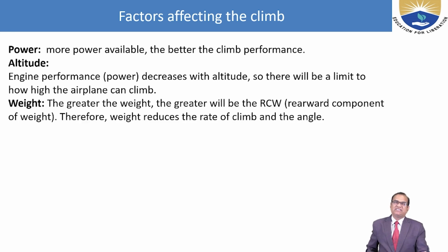Weight is also very important, because just now you have seen that weight is everywhere. The greater the weight, the greater will be the RCW, the rearward component of the weight. Therefore, weight reduces the rate of climb and the angle.